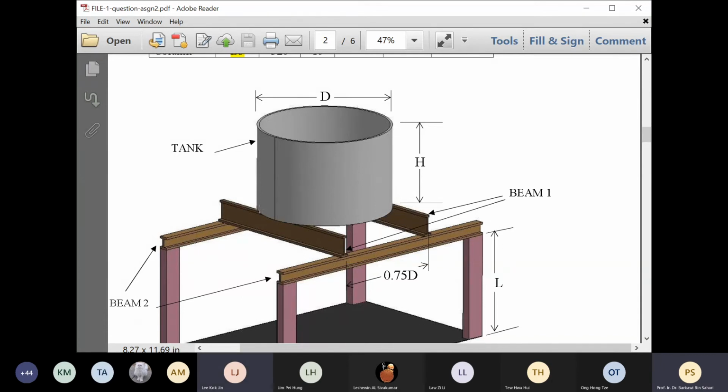We just use the weight of this tank and then divide by the meter. Well, it doesn't cover the whole length of the beam, it's just a small part of the length, so we directly divide by that length. Because there are 2 beams, in other words, one beam carries half. So we need to divide the weight by 2, then we need to divide by the length where the tank sits on the beam. Yes. Okay.